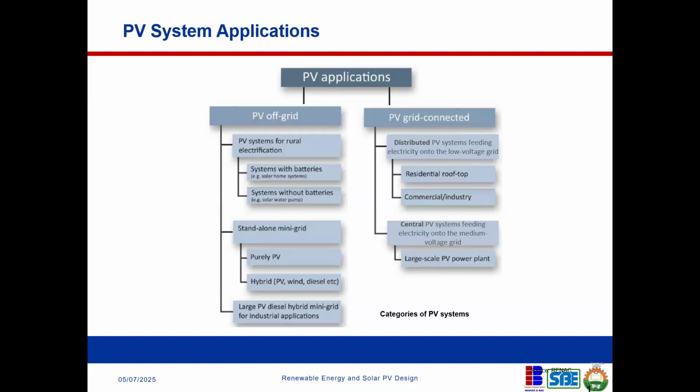And it's a hybrid system, meaning that it has multiple sources of energy supply. So in the case of that industrial complex in Ibadan, they have a solar PV system, they have a generator, and they also have the grid. Okay, so now let me add that when you have this kind of configuration, in most cases the solar system cannot function independently. So the solar system needs the grid or it needs the generator to run in most cases, right?